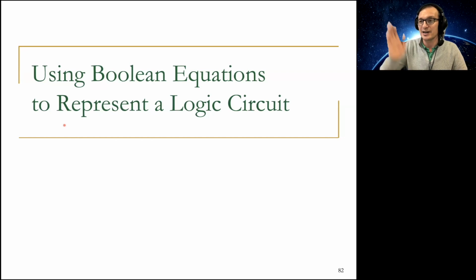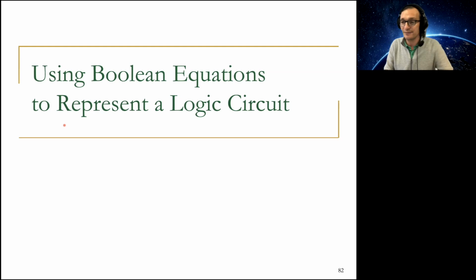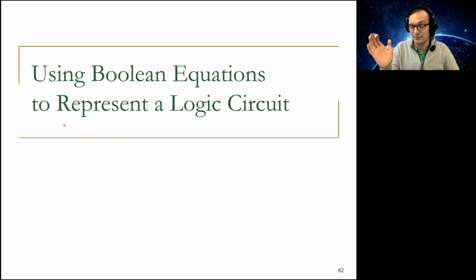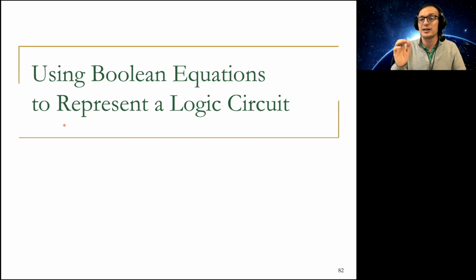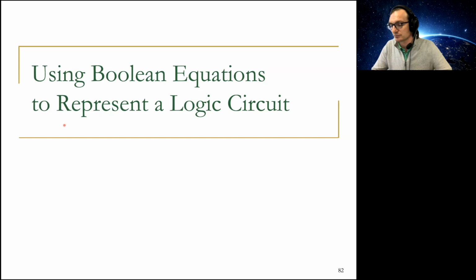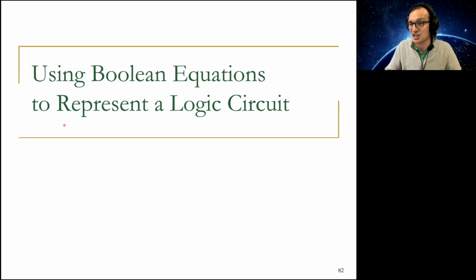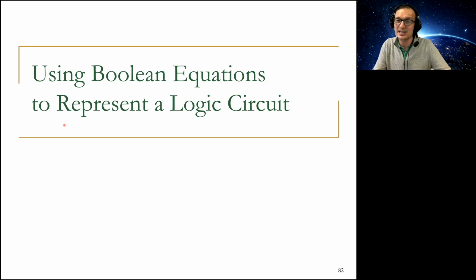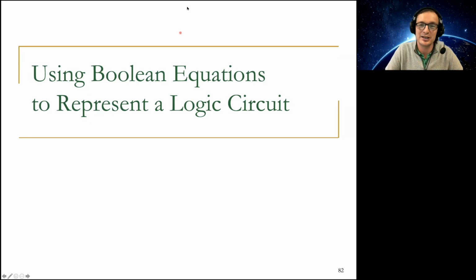Essentially, you're increasing your F. To be able to increase your F to very high values, let's say 10 gigahertz, 100 gigahertz, you need to be able to increase your voltage. So basically, your power increases in a cubic fashion with the voltage or with the frequency, let's say. As a result, you get a huge power consumption if you want to increase the frequency.